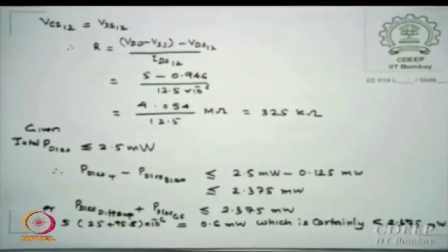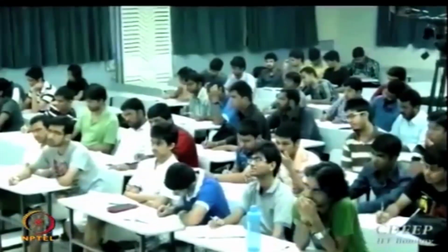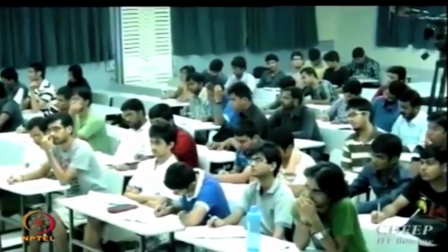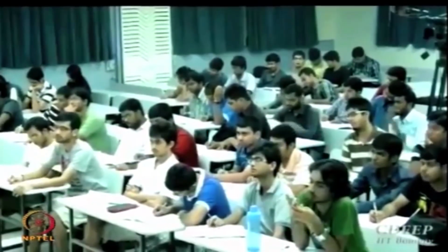So what is the next game you can play? Increase currents for a higher slew rate, then recalculate all values of W by L and see whether they still remain in saturation but satisfy conditions better. Is that correct? Because at the end of the day this may be sufficient, since low power is one of the major criteria, so we are anyway achieving it.